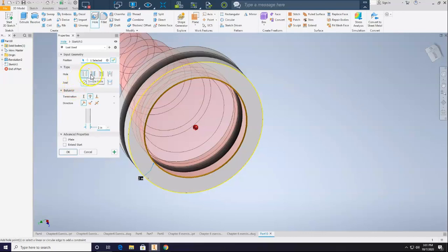So we've only done simple hole. We can also do tapped holes, like with threads. We can also do taper tapped hole. Did I say taped? I meant tapped hole. Taper tapped hole right here, where it's doing both moving in at a taper angle as well as giving you grooves for your screws. You can also have different seats, counterbore, spot face, and then countersink.